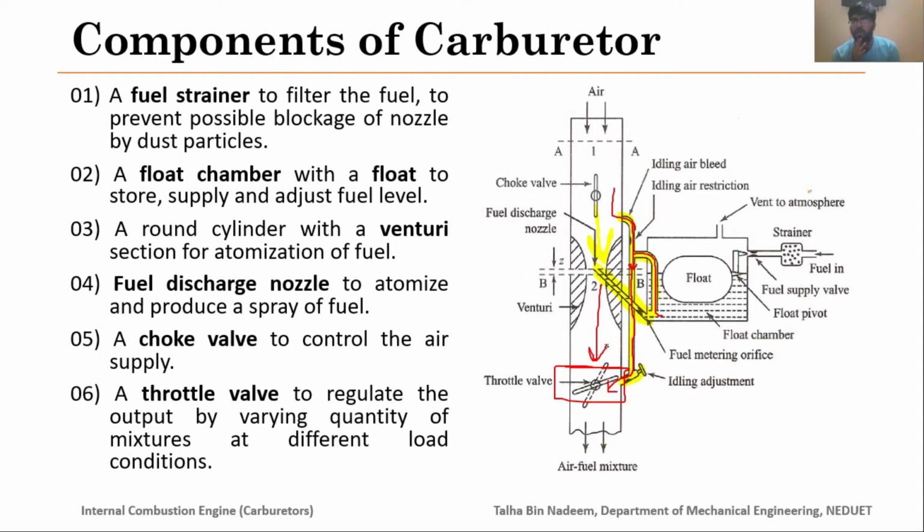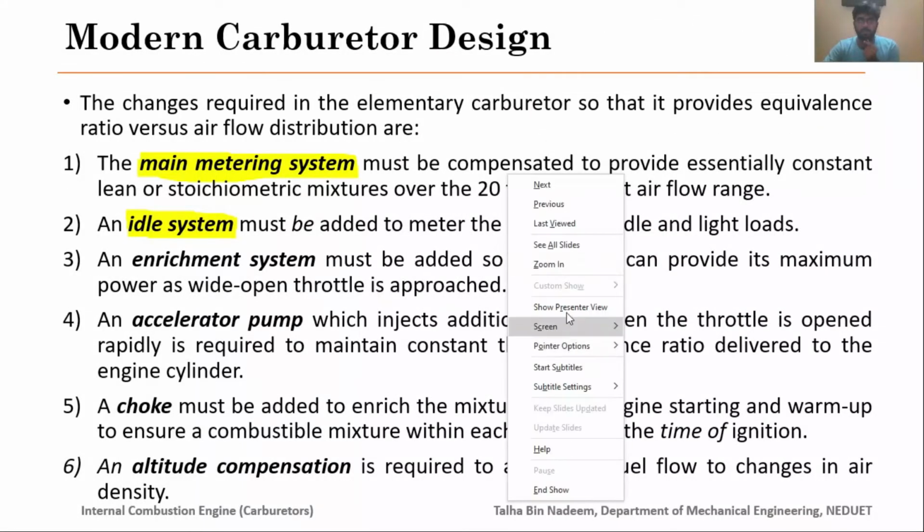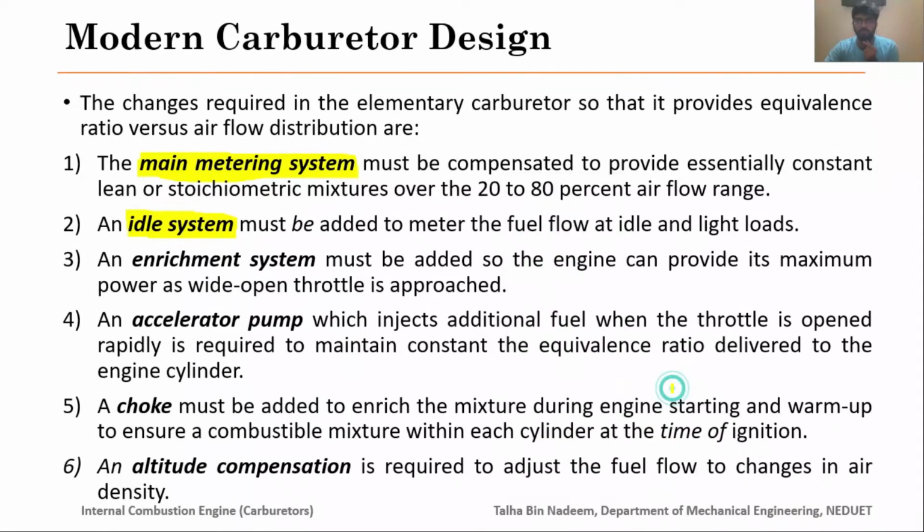So this additional idling system is providing that much fuel, so it is providing you a rich air fuel mixture at this point, and it will move to the intake manifold and then into your combustion chamber.